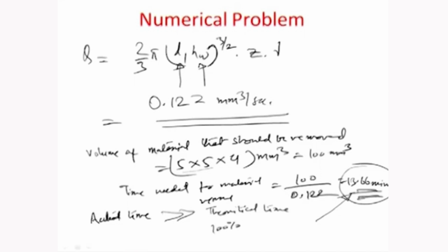That means one impact is producing a flow, but that may not be the case, because if there are a lot of abrasive particles packed in the slurry, there is a possibility of intergrain collisions, and collisions with the debris which gets generated. There is a huge amount of chaos or randomness in the system of the particles and debris floating around in the slurry material, and therefore the amount of material removal may not really vary proportionately with the amount of grains which are impacting the